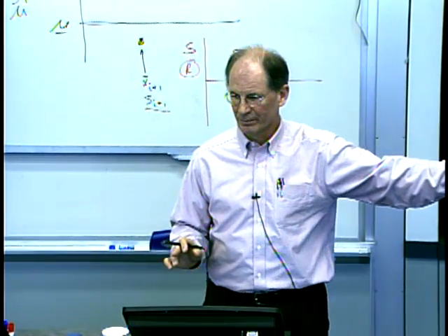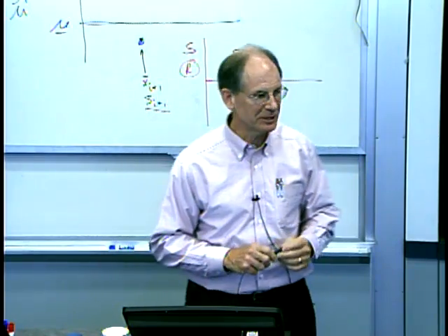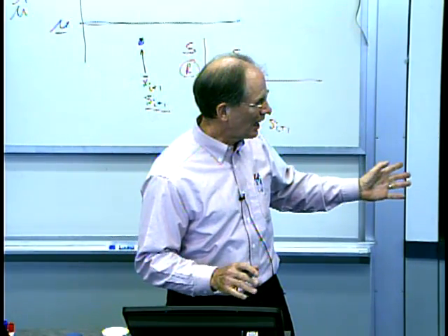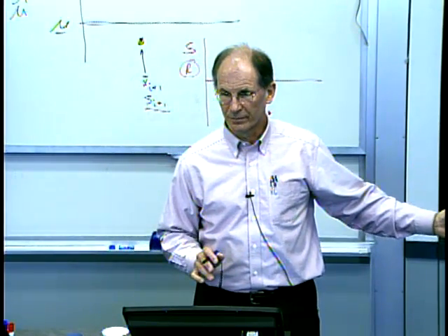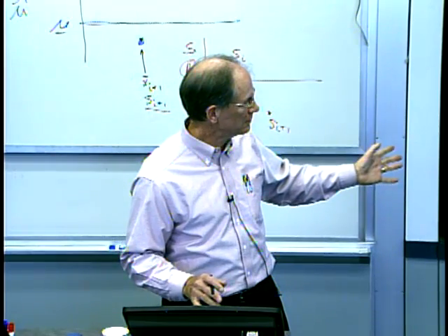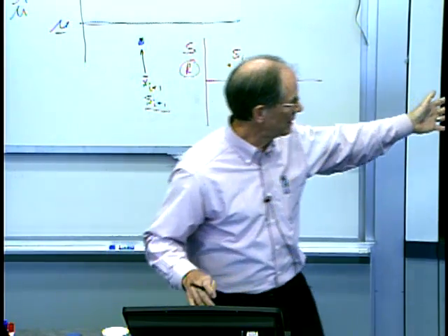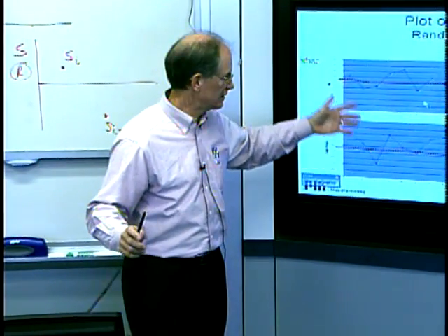This has already happened. So the first thing I need to do, and this is part of the art of SPC, is look at that and say, does it look like it's in a state of statistical control? And frankly, at this point, you eyeball it and you say, well, I don't see anything that makes this look non-random. And we're going to quantify that in just a second.